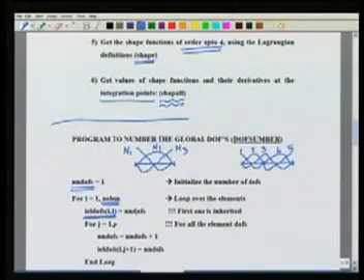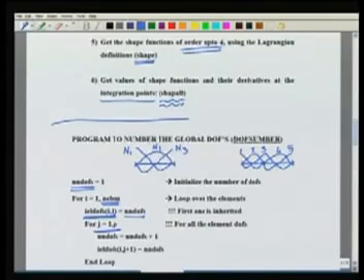So what am I going to do? If you see, for element 1, here I said ILDOFs(i,1) is equal to NNDOFs. What does it mean? For element 1, the first degree of freedom of element 1 corresponds to the global 1. Okay. Then I go over the remaining p degrees of freedom in the element, and I keep on constructing these global degrees of freedom and updating my element to global connectivity. So you see that I am looping over j equal to 1 to p. I increment the NNDOFs, that is the total number of degrees of freedom, remembering that I should not repeat this increment, so that 1 degree of freedom should not be counted twice. So I increment this degree of freedom count.